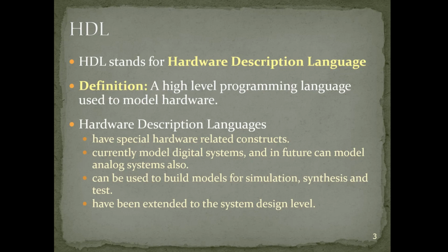What they are also very good at, and this is part of the whole idea of creating complex designs in quick time, is that they can perform simulation quite extensively to make sure that our designs behave exactly as intended. And then once we are satisfied that our designs work as intended, we can proceed to the synthesis process, which actually generates the programming file that configures a CPLD or FPGA device to behave in the way the program tells it to behave to create that particular design.